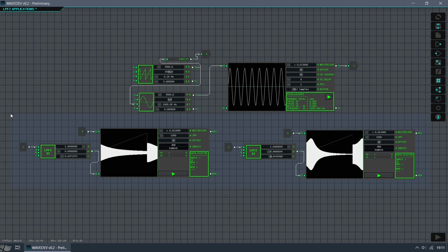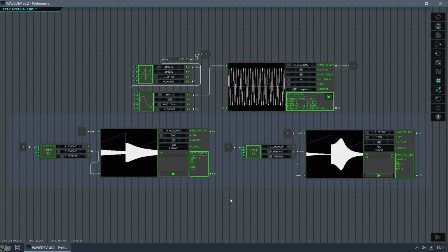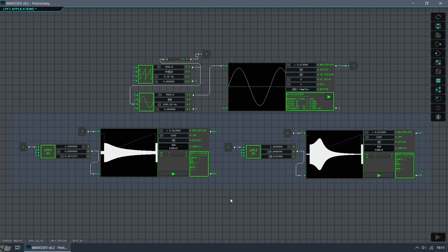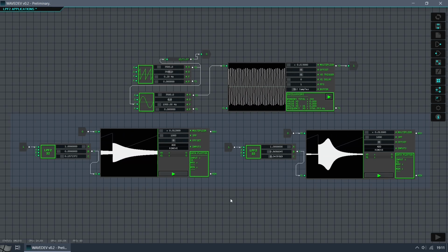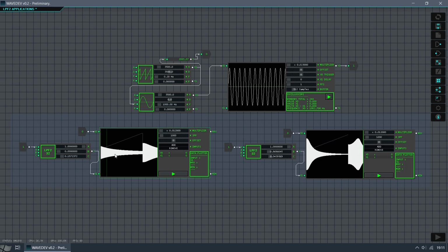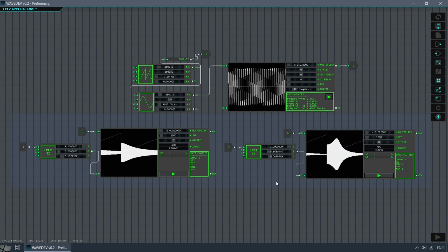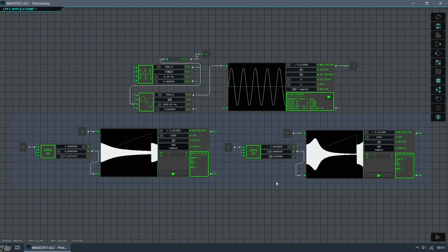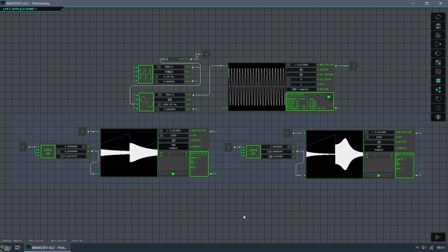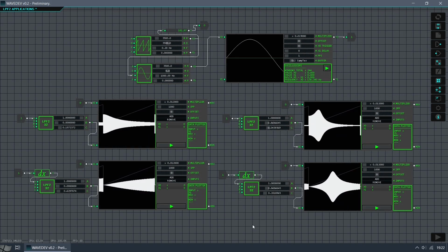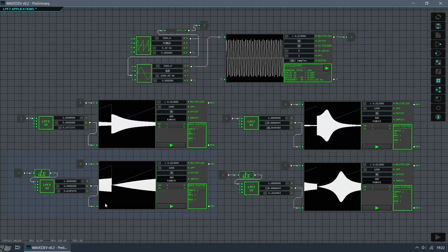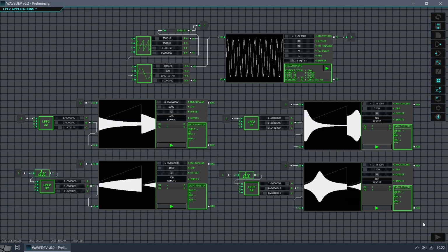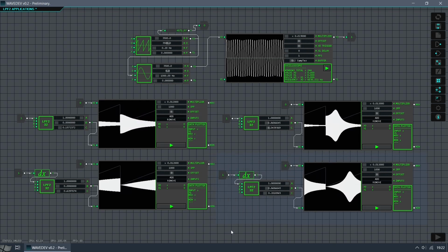These two filters have also their inverses, which correspond to the high-pass filters. I will show you a simple and cheap method to get them from these. We are going to precede them with a derivative. And the same logic applies to both filters. First-order high-pass filter and resonant high-pass filter.